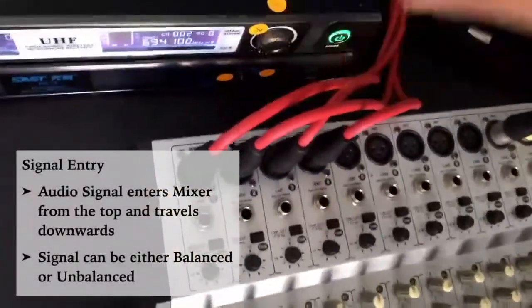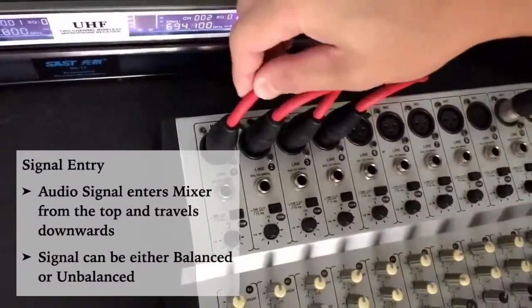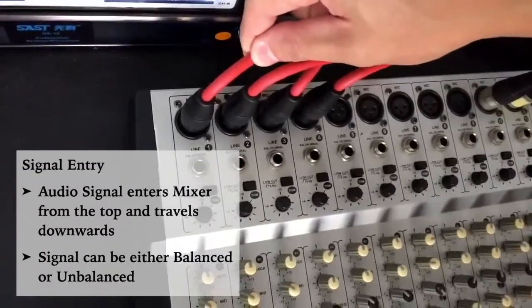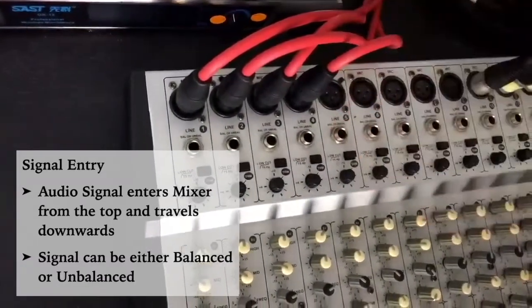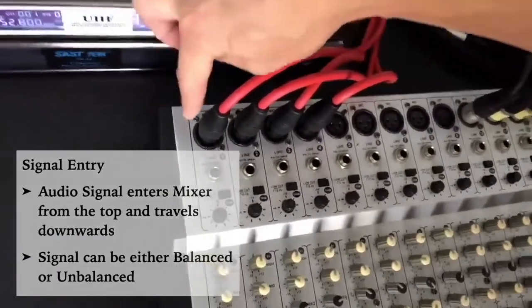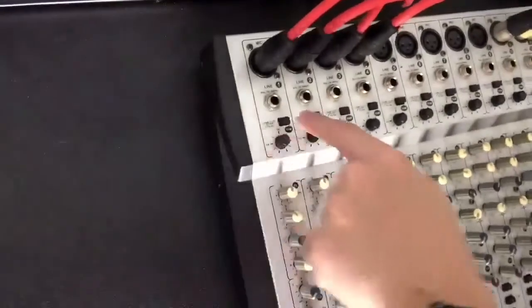We start from up here. The input comes in from here. This is an XLR cable, okay? It carries a balanced signal from the mic, and it can also carry a balanced or unbalanced signal from whatever sources you want to give it, okay? In this case, it carries the balanced signal from the mic. It comes in from here, and then it immediately goes to your low cut, okay?